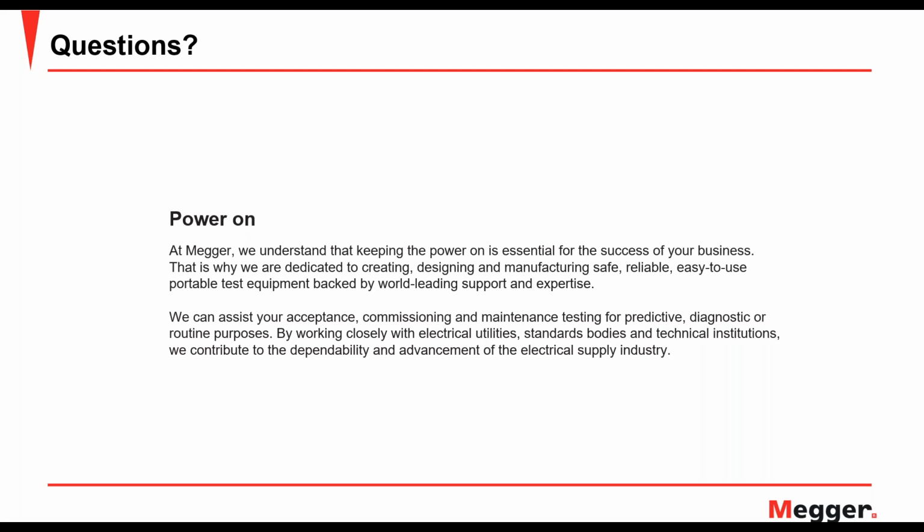But that's where the similarity ends. They are variable frequency tests, but they do entirely different things. What the DFR does is it does power factor testing at different frequencies, and you get a plot. But it does power factor testing, which involves loss measurement, right?